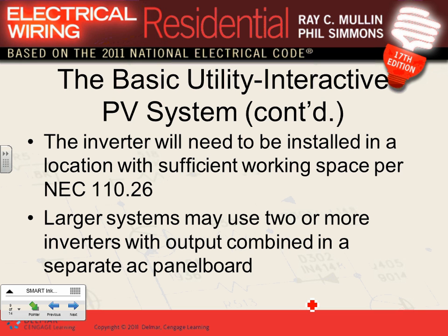Now remember the inverter we were talking about. Everybody knows what the inverter does. It takes the DC into AC. You have to put it in a place where you have at least 3 feet of clearance in front of it, like the clearances in front of the panels, because you need to work on it. For the commercial building that you guys are going to do for me, only the A students are going to do it. The B and the C are excused.